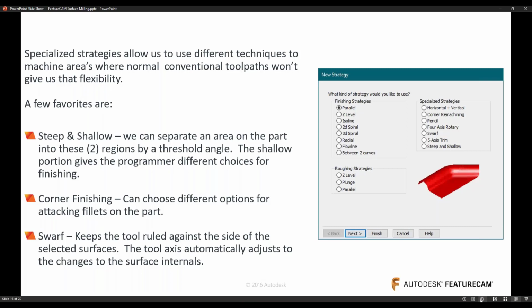So the important aspects of this toolpath are that you have good swarfable surfaces. So it's got to be nice and ruled, like flat planar surfaces. Doesn't have to be vertical, but they just need to be nice planar surfaces. So if you get really bad results when you use Swarf, it's most likely because the surface data is not good.